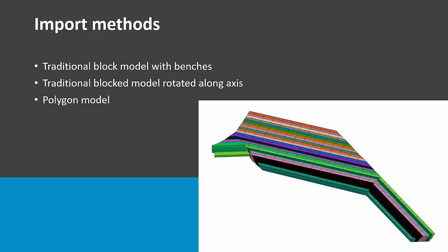This is actually newly released in Scheduler. We've had internal versions that clients could use as needed in order to bring in their reserve sets with polygons in Scheduler. This is an example of what that might look like for a strip-oriented operation. The only downside is you need to make sure that you have structured that data correctly, where you have large enough polygons that you're not going to overwhelm Scheduler with the choices, as David was talking about earlier. Going forward, I'm going to be talking about this Polygon model that I've made.